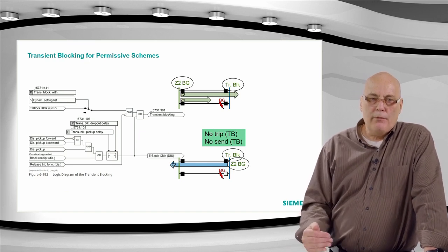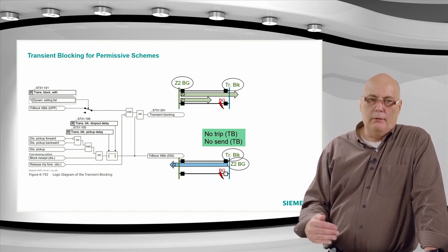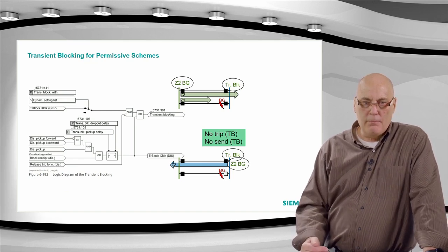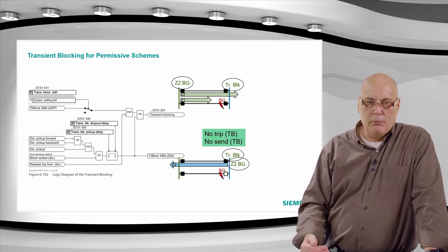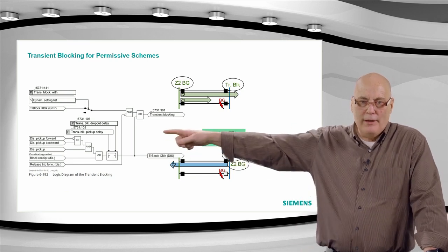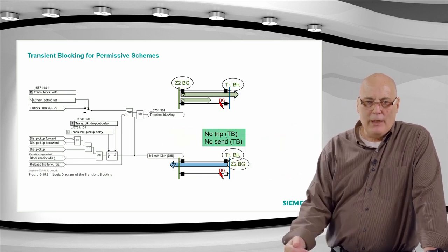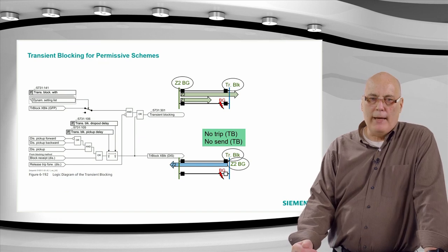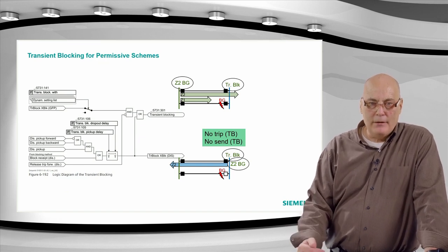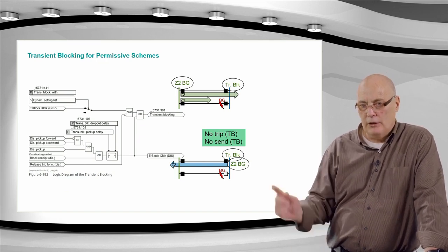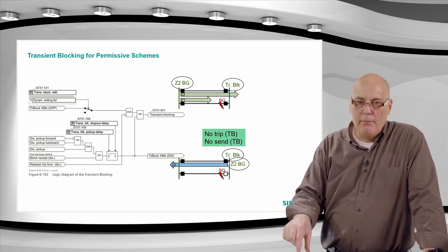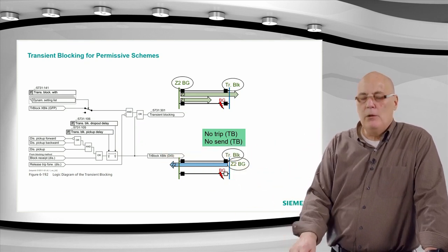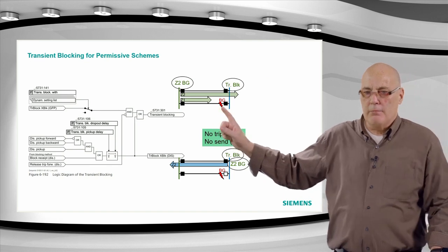You can see there, if you have a pickup that is not forward, or a pickup that is backup, that's an OR gate as such, and you have a general distance pickup at the bottom, those 3 inputs you see over there on the logic. Distance pickup not forward, distance pickup backward, or distance pickup backup, and a distance pickup. Those 3 conditions give you the input to the timer. And if the time delay is exceeded, then you would expect that must be a reverse fault.